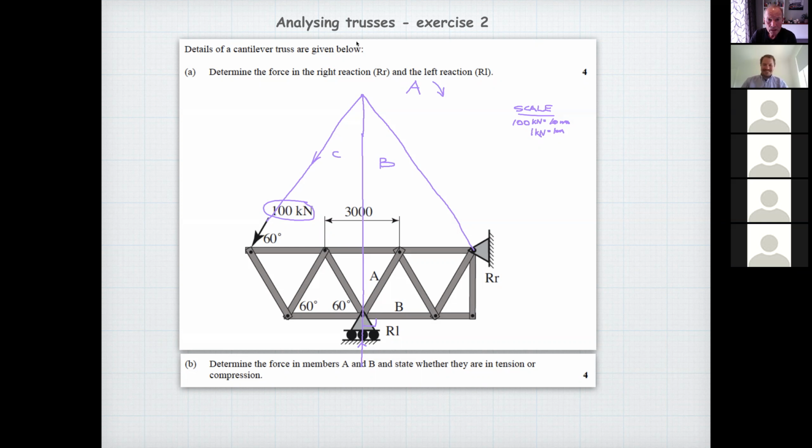And then now, can I change color? Yeah, I don't think I can. Oh, yes, I can. Okay, so this is the known force, so I'm going to draw this 100 millimeters long, put the sense on it because it's shown, and this force is CA. C is the tail, and A is the head of the force. If you do this, it's just like joining the dots on a donkey.